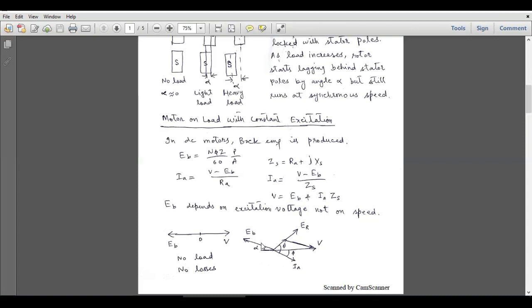Now this is the back EMF. So in order to conclude this expression, which is saying that V is the vector sum of back EMF and the reactance voltage, V is equal to EB plus ER. So we have to place this back EMF vector at the top of this applied voltage vector. So this is EB, and now we have to produce the EB dash vector. The EB dash vector will be opposite to that EB vector, which is exactly anti-parallel with this EB vector, and this is the EB dash vector.